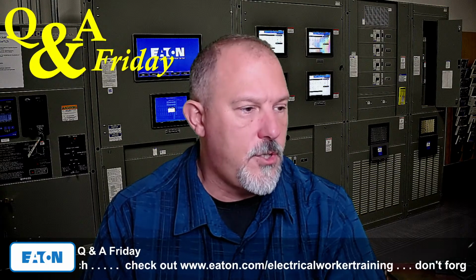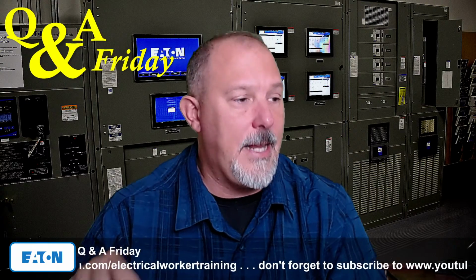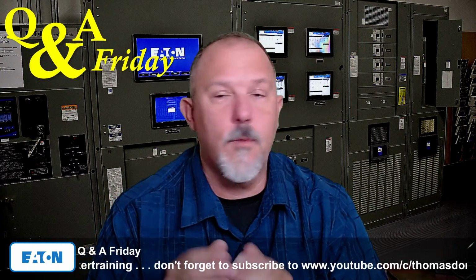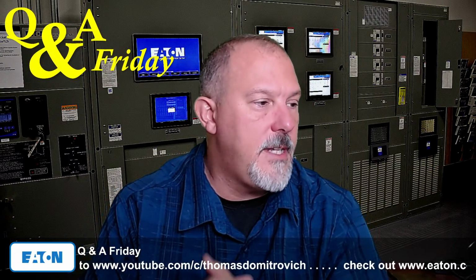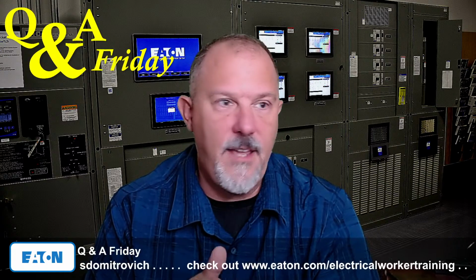I had understood that the %Z is basically what percent of the transformer's available short circuit current it is able to deliver at its rated load. So if you take rated kVA and divide that by %Z, then you get short circuit kVA. I fail to understand the statement that %Z should be the same at both kVA levels.